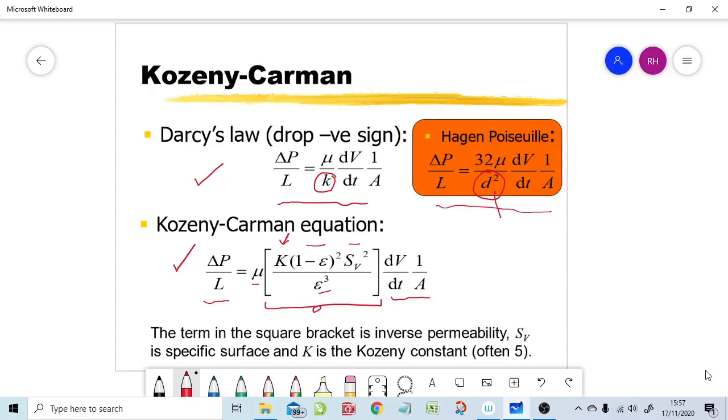An additional thing to point out here is that this assumes no turbulence in the fluid. So we know that this is only valid for a Reynolds number, which is always the ratio of inertial to viscous forces, that is less than the appropriate amount for the threshold of turbulence. In our case, this is what we call the modified Reynolds number, not the flow Reynolds number of Hagen-Poiseuille, but the modified Reynolds number, and the threshold is 2, not the 2000 that we see in flow through pipes.